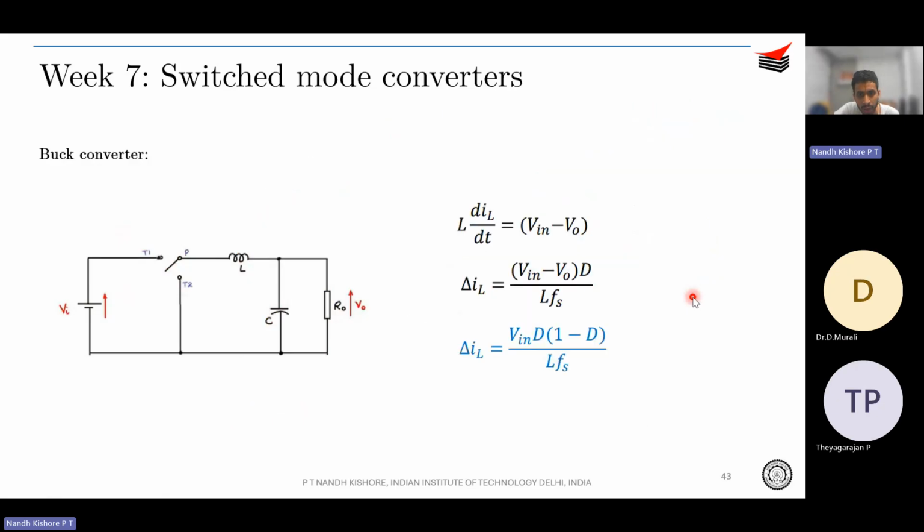First of all, you studied how to obtain a particular value for L. That is based on the ripple requirement. If they say the ripple requirement is 10% or 10-20%, based on that you will compute the value for L. Again, the computation is simply based on V equal to L dI by dt.